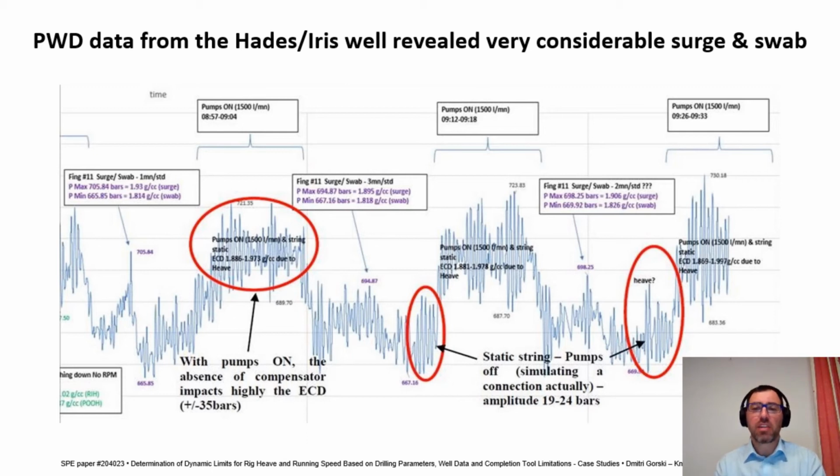This heave impact on the fly should adapt to the current drilling circumstances as well as BHAs, well depth, and maybe also changing borehole configurations. We got in touch with Heave Solutions and asked them to do a post-study for this very same well. The major and very important difference between the first study and the one done by Heave Solutions is the dynamic rig heave approach they presented to us.